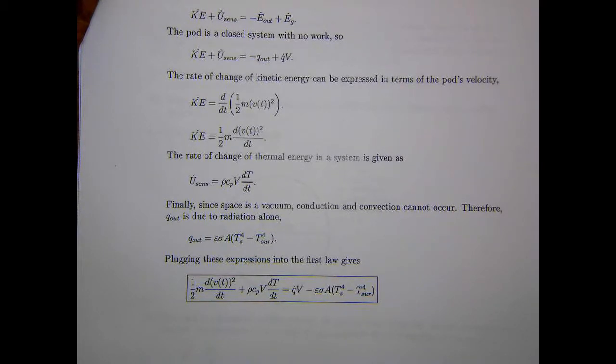Okay, questions on this? I think there's still a little bit of a fundamental misunderstanding about stored energy, especially thermal energy, and Q, heat transfer. So thermal energy is the energy that's inside of a control volume, or internal to a control volume. So stored energy: kinetic, potential, internal. And then thermal energy is how much of the internal energy is due to sensible or latent components. So that's the motion of the molecules or energy due to phase changes. And then heat transfer is that energy in motion.